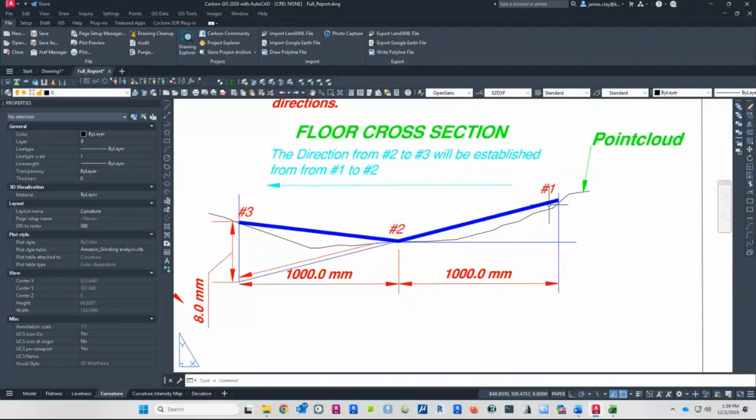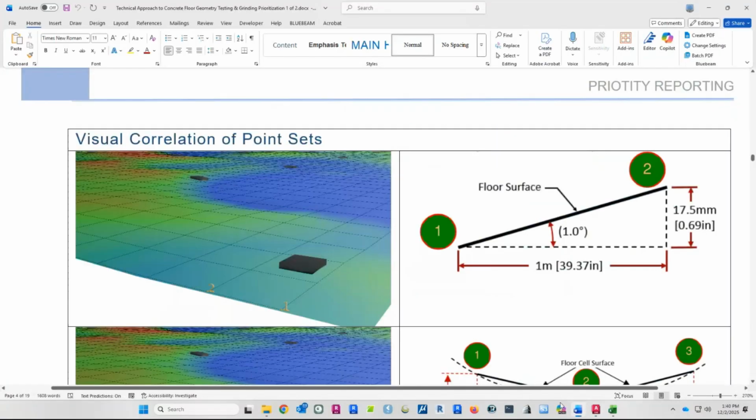But so how can you remediate this? You bring the high side down to try to get rid of this bowl in the floor and feather that in. That's what the remediation teams want to look at. And that's how they'll go back. So the cut's there, and then those slopes are published on each side to kind of give them a hint of just how steep that failure is. And one quick thing I meant to go over just real quick, just a better feel for this.